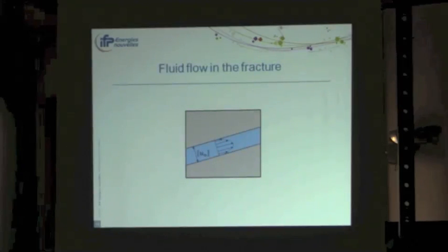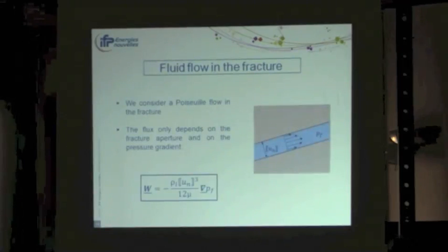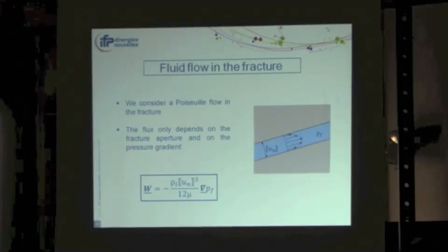For the fluid flow in the fracture, we are only interested in the expression of the flux, and we consider the cubic law for the flux. The flow in the fracture depends on the cube of the fracture aperture and on the gradient of the pressure in the fracture.